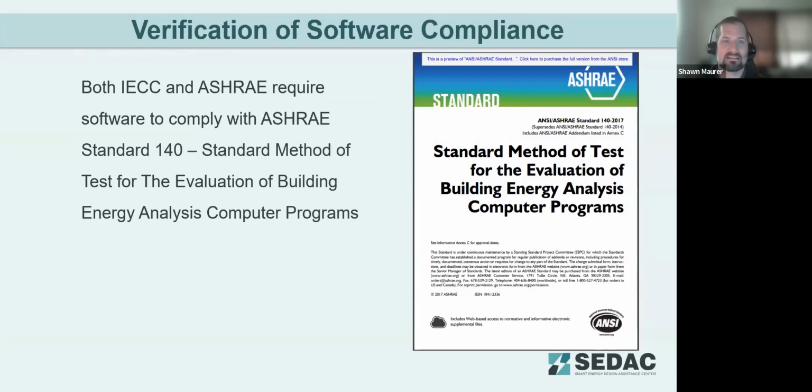Both ASHRAE and IECC do require verification of software used for modeling purposes. So in both instances, they have to be in compliance with ASHRAE Standard 140, which is just a standard program for evaluating building energy models, sets up requirements for them in terms of hourly simulations, how accurate they have to be with a reference model. And so this requirement is similar for both the IECC and ASHRAE. It's listed in both the general requirements.